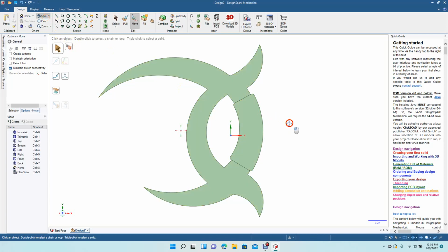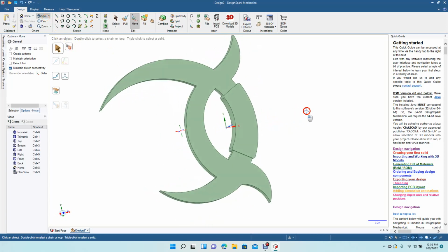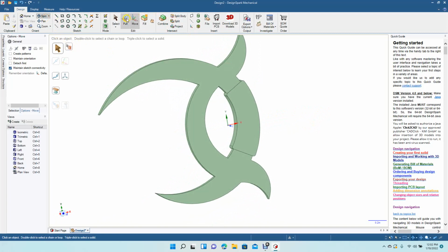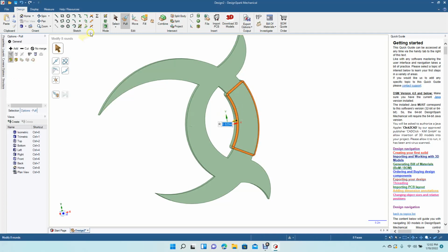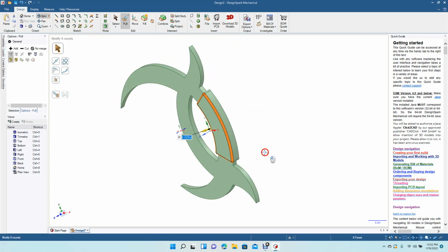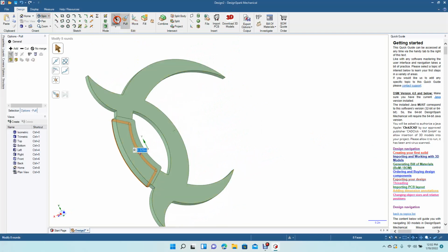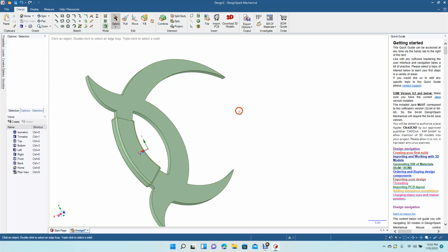Now we'll spin. That's where it needs to be. So now I'm going to add some fillets. Let's click till everything's selected. Click and drag. We'll go 0.20. I'll put a spin in here. Let's pull. Let's do the same on the back side. Oh, 0.020.